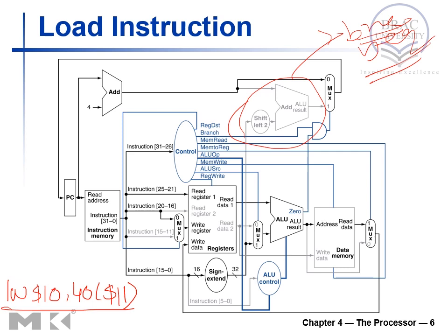But see, the memory unit is active now. In R-type instruction, it was inactive, but now for load instruction, the memory unit is active. So when we are performing load instruction, ALU generates the memory address. This is not generating any data.